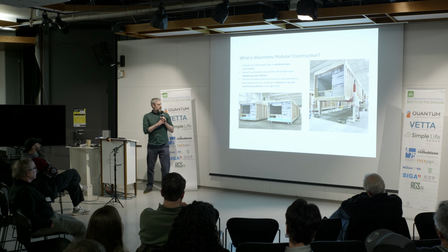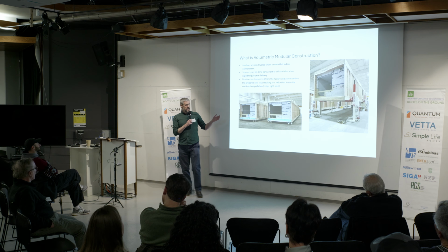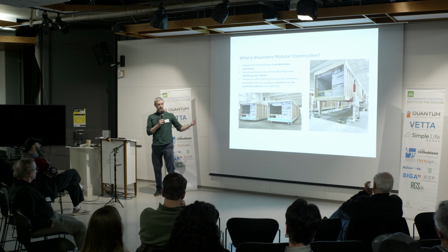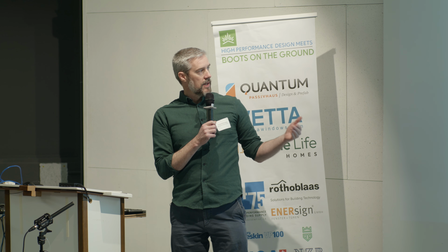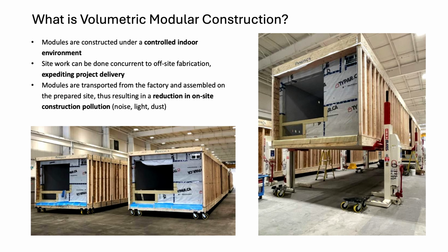In this instance, the components, so maybe the walls and the roof, were essentially flat pack elements that arrived at the factory, and then they were put together to form a 3-dimensional box. The box was finished on the outside with insulation and membranes, on the inside with drywall, and in many cases with the equipment, the refrigerators, the cooktops, the kitchen, and the finished furniture.